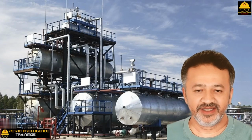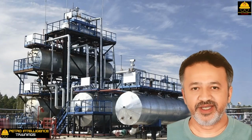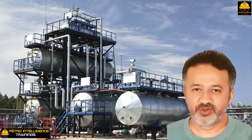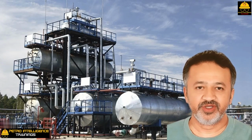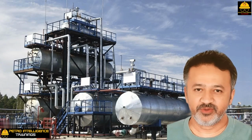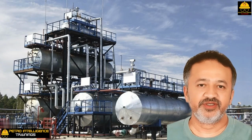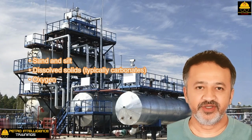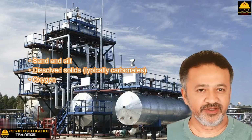Boiler feedwater and its sources. Steam is generated from boiler feedwater. But water used for steam generation must first be purified. For example, raw water drawn from the river has 3 objectionable contaminants: sand and silt, dissolved solids, typically carbonates, and oxygen.